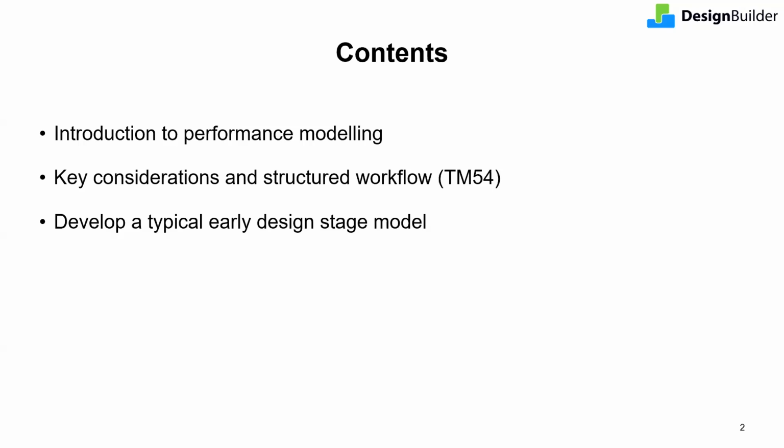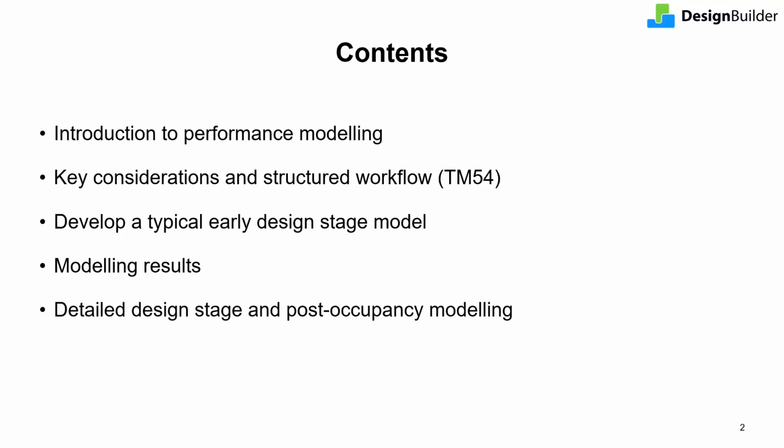So while my focus is on TM54 and its process, the key concepts for your protocol will be similar to guides such as NABERS or ASHRAE 209. We'll also be looking at ways to present results for better and cleaner communication about projected performance for more informed design decisions. And finally, we review modeling done at advanced design stages with detailed systems and controls, and also look at the role of building performance modeling in performance evaluations after occupancy.